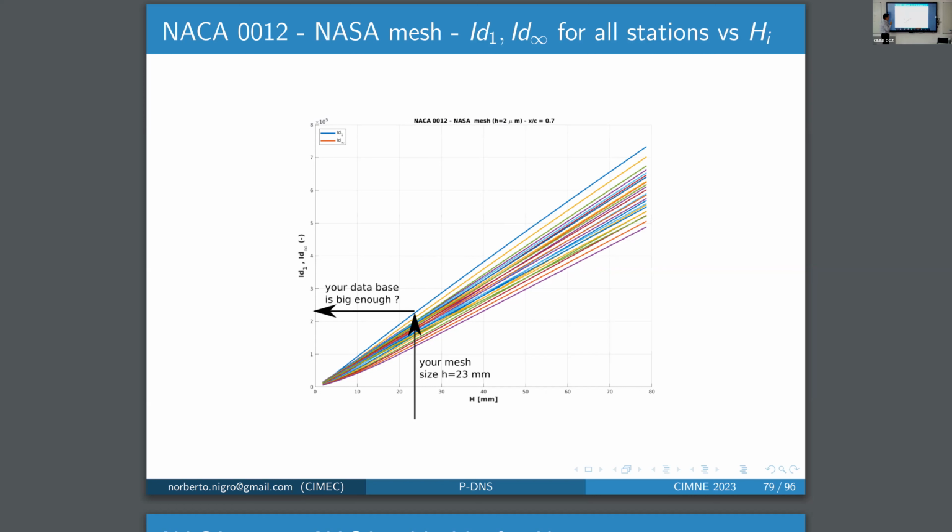What is important is, if you have a database built with information that only goes up to 200,000, the limit of your coarse mesh should be 20 millimeters. You don't have to do simulations with a mesh coarser than 20 millimeters, because you lie outside of the database and your results are in a danger region. So this is some sort of previous indication about how coarse your mesh can be in order to get a solution that uses good information from the database, and not garbage. You know?